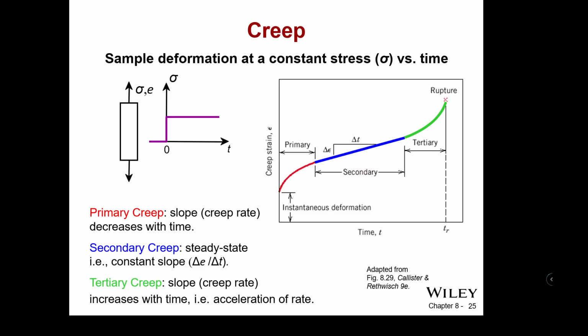so that you can measurably see the difference between the top of the glass in terms of thickness and the bottom of the glass. So the bottom of the glass is where a lot of the material will collect as it continues to creep over the course of time. So over a very long time, you have more and more strain built up in the material. You can reach a point where, depending on what it is, you can have rupture.